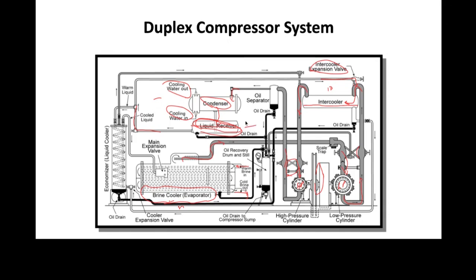So it does, in fact, radiate heat out into the room. So there's some subcooling going on in the liquid receiver, which is a good thing, but it's not good enough. We want to make it even more subcooled. So notice we've got warm liquid, which is still subcooled, coming from the liquid receiver, and we want to put it here into the evaporator.